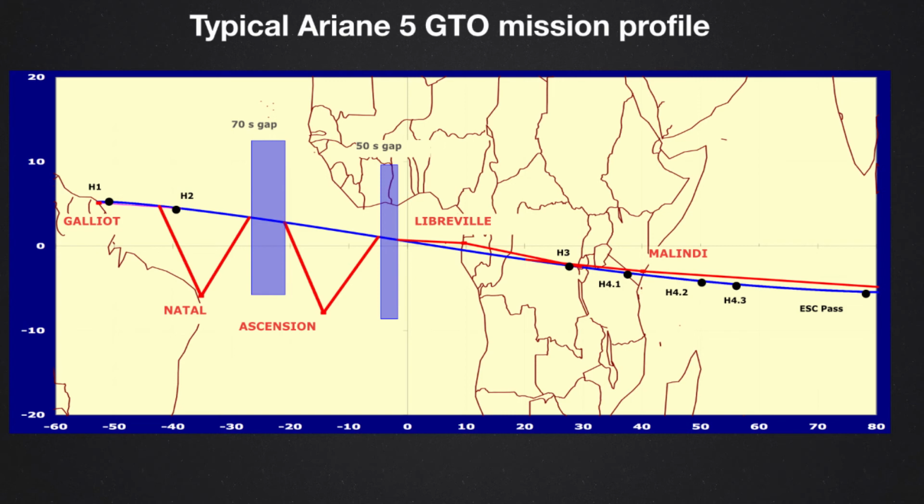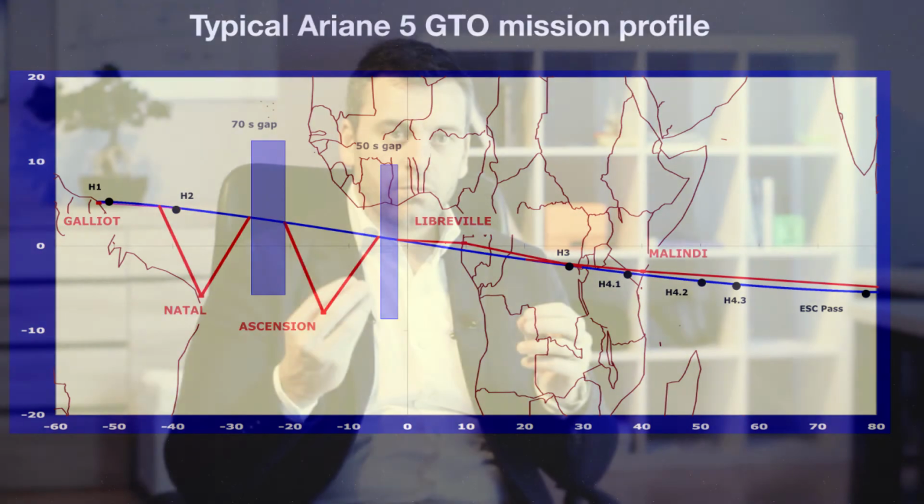This is about the visibility issue, as I already told you. So what happens lately is that we took into consideration the fact that we can lose some telemetry, and we can live with the fact that during some very steady phase, when there is nothing happening, we can basically store some of the telemetry on an onboard mass memory, and as soon as we become visible to the next station, we can release all the telemetry bits to the next station.